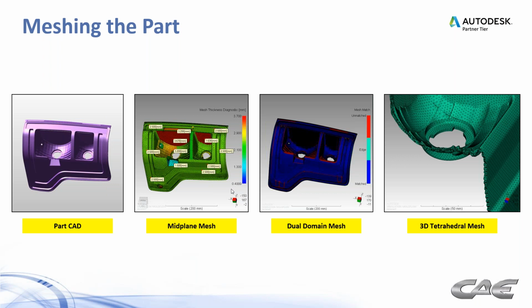But you can see there that in many cases, you don't have as good a control over how that matching process works. And if you don't, then maybe you need to recondition your part to allow the matching process to work out a little bit better. Those areas in blue are well matched. The areas in red are not well matched, so it's not calculating the wall thickness well in those red areas. So in some cases, midplane is better because you have a little more control.